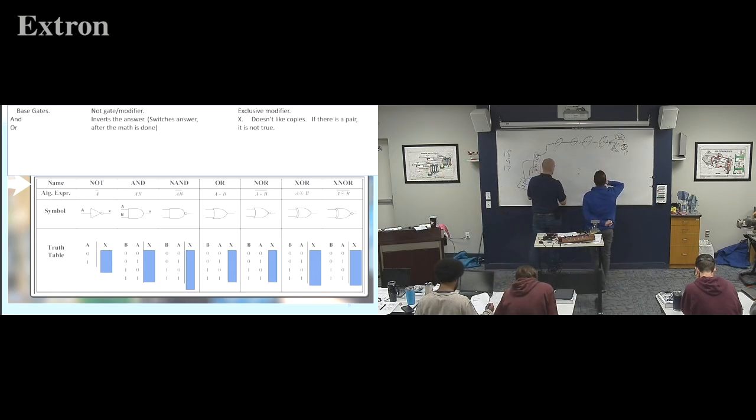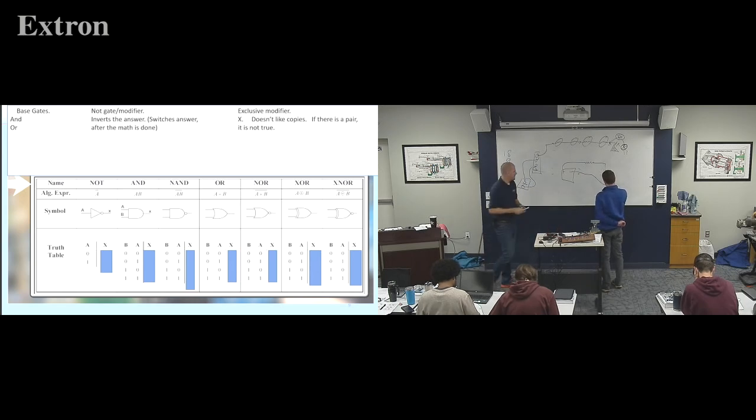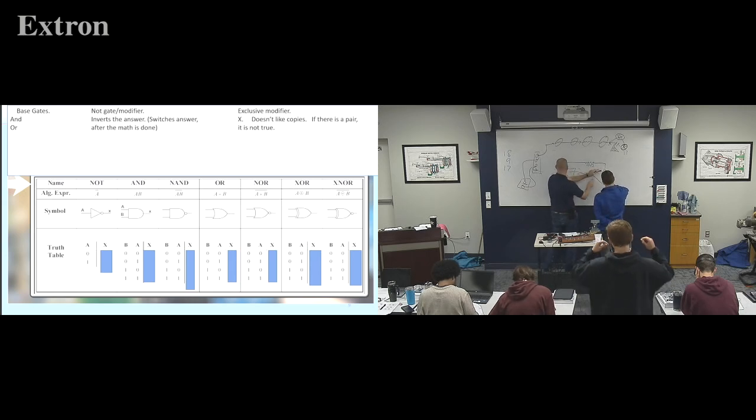Yeah, so if we simplify it, just down to a battery, plus minus, resistor, and a switch. If our switch is open, what would we read here? So, 12 volts? Or so 10 ohm, we'll say. We would read 12 volts, but there's 0 amps. Yes, but whatever word you wanna use. So with this open, with a voltmeter, obviously, yep, so 12 volts with a voltmeter.